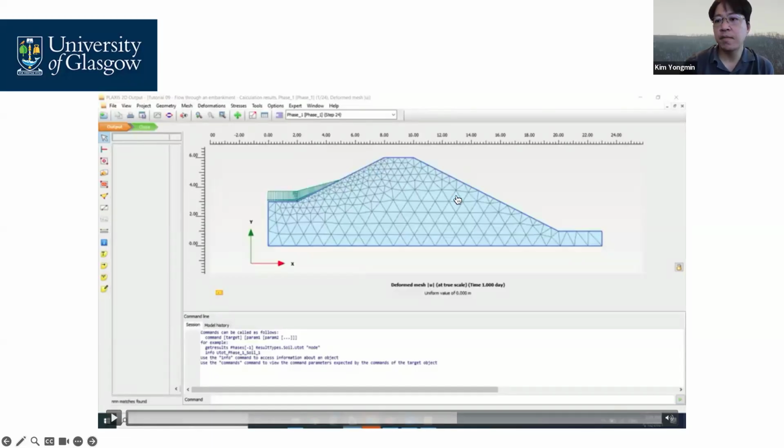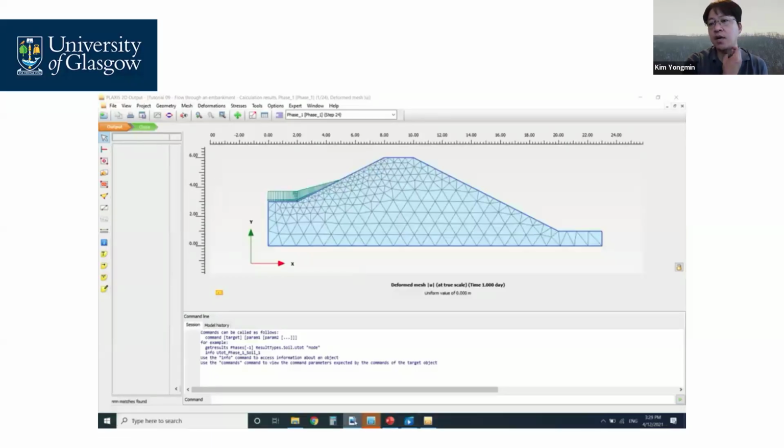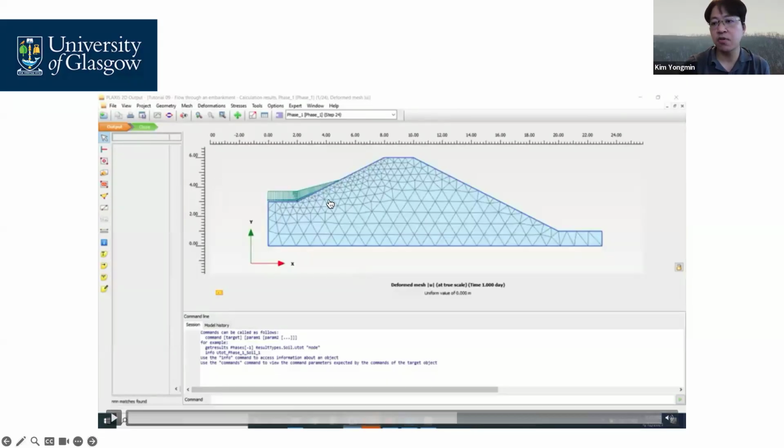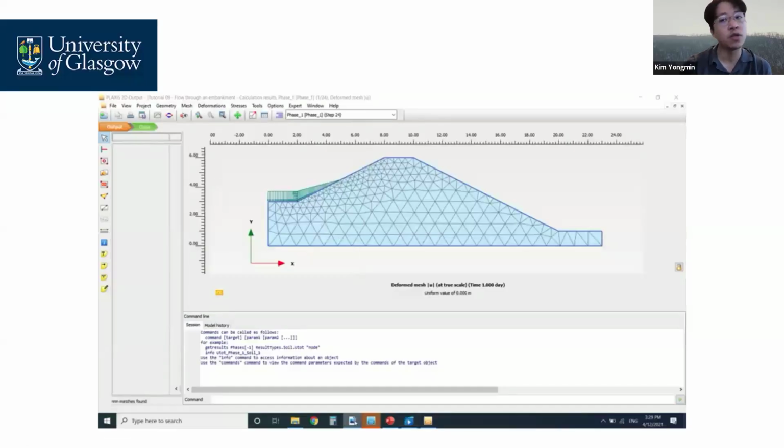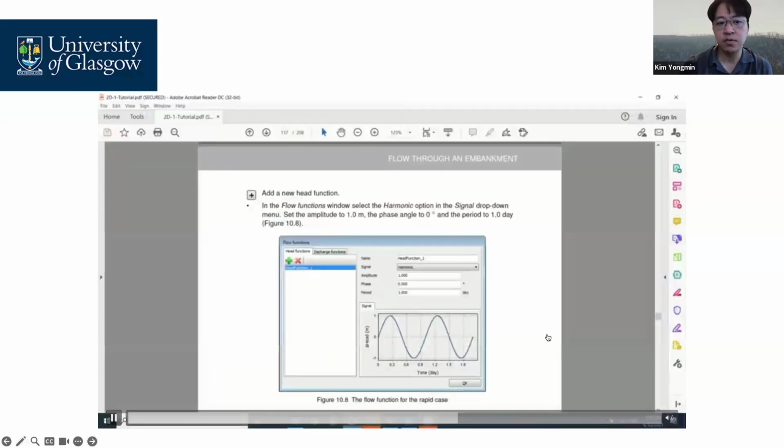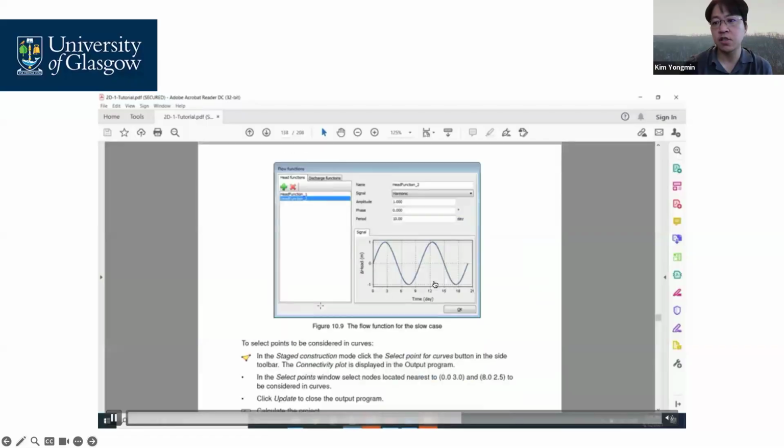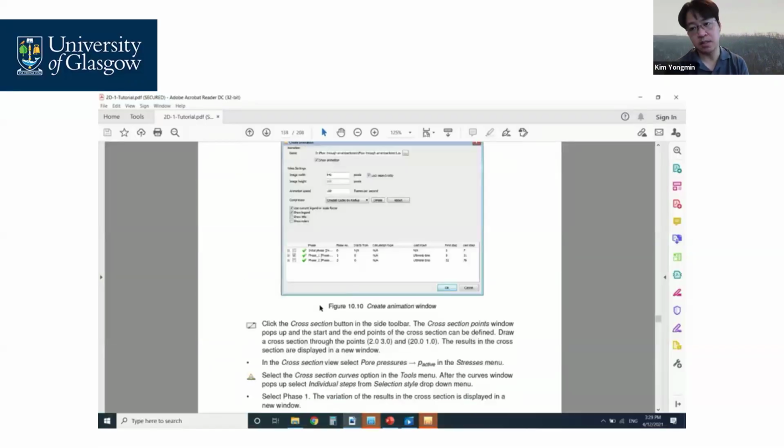This is a finite element mesh. So we also name this kind of software as finite element method. Each element calculates the water flow rate, water pressures, pressure head, and total heads. This is quite similar to our Flownet. So let's continue. We can see certain output from each element.